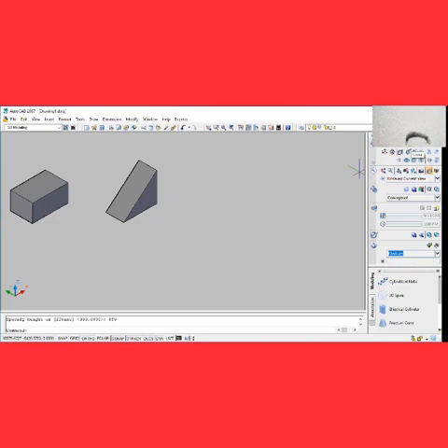So now if we take this, we have it as cone. Now it's telling you to specify the center. At the command window we are being told to specify the center point of your base. So your cone can be circular based and it can be elliptical based. So now if you have to use circular base, we can just choose the center immediately, C, and then enter.